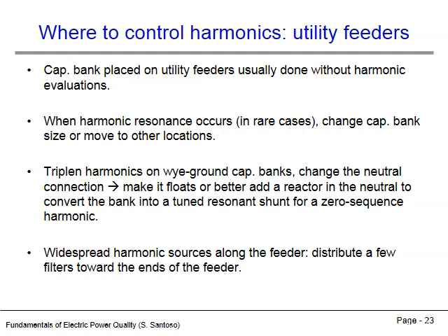Certain harmonics, called triplen harmonics, can be blocked by installing delta-connected transformers in place of grounded Y connections, or by adding a reactor to the Y transformer's neutral connection. Finally, filters can be added at the far end of distribution feeders to draw problematic harmonic currents away from the upstream power system.